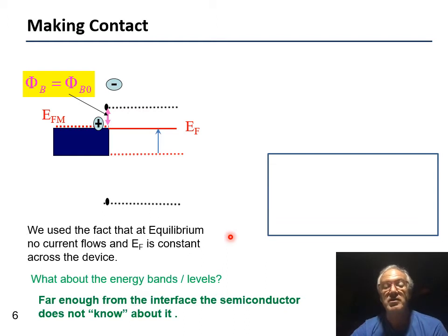So basically, the Fermi level is supposed to be at the same place relative to the conduction and valence band as it was before we made any contact. So we know where the bands are going to be far from the interface. We know that we place them close to the interface really the way they were before, and that's how we created this energy barrier. And basically what we need now is to connect the dots, and this is what the bands would look like.